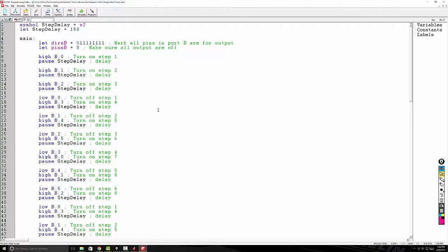Of course, you can use this for turn signals. You can use this for whatever other projects you like. But you can program the lights with infinite flexibility. And you can even use the PWM pin on the microcontroller. Some of the PICAXE models have PWM outputs, and you can figure out in the BASIC programming language how to use that to your advantage to maybe fade lights on and off, or whatever other effects that you want to achieve. So that's pretty much it.